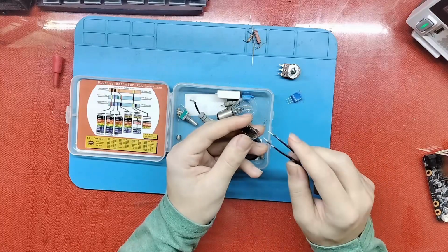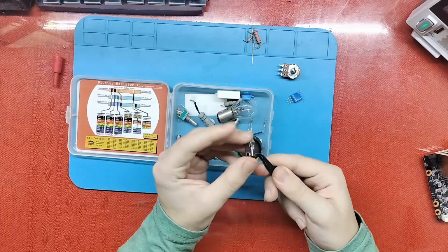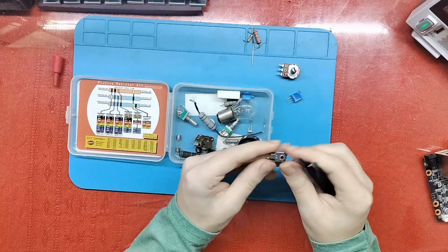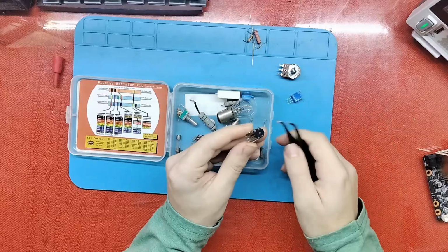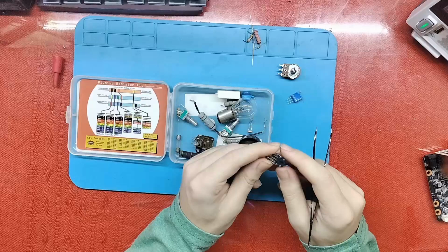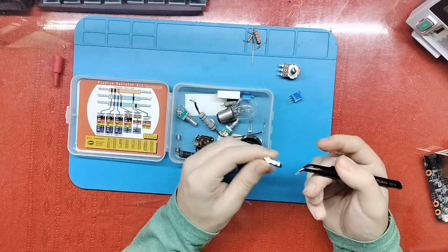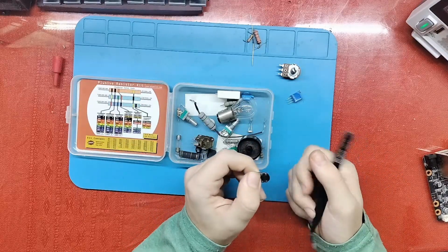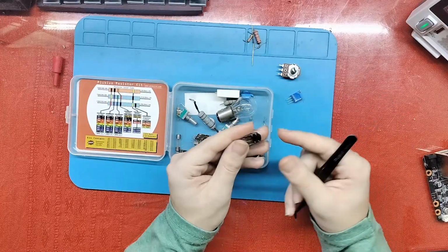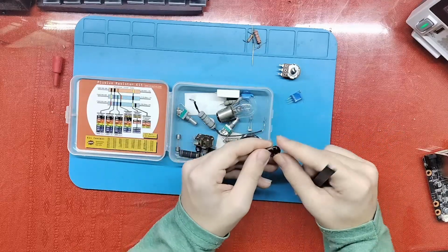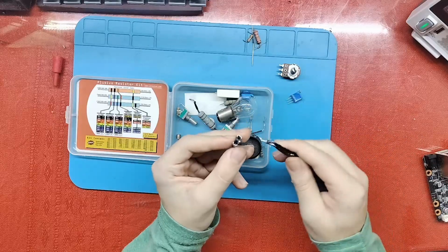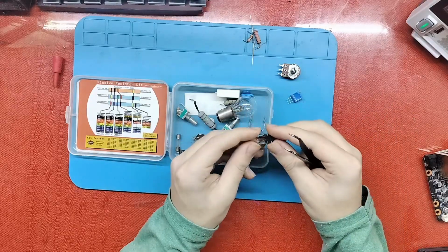It still has a place which you spin it by, but it's not a potentiometer. It's a completely different thing, and it's not gonna go very well if you use one of these instead of one of those. So be careful. If you don't find an ohms value and it doesn't have an end stop, it's probably an encoder.